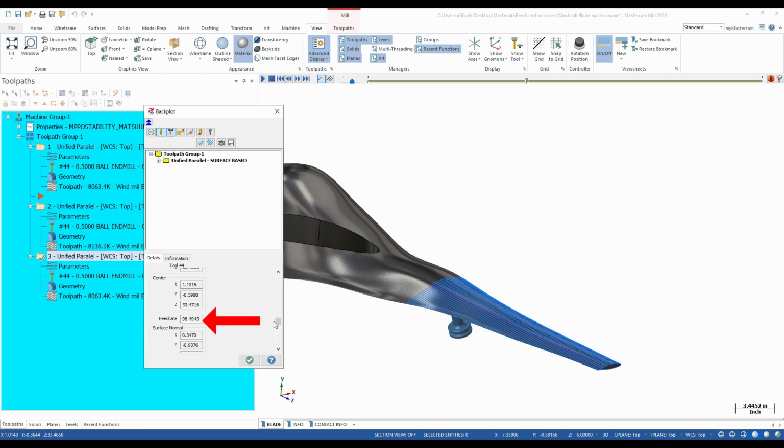So now you're seeing a feed rate right there of 98.49. As I go, you're going to see my feed rates are altering as I'm going because of them parameters that I set in there, and it's reading all of that data off my model, seeing what the radius is and where I am in them percentages. So as I get to a sharp corner here, you're going to notice that we slow down. Now I'm down to 10 inches a minute. Now that's a sharp corner. I told it 10% of my feed rate on a sharp corner, and that's where it picked it up.